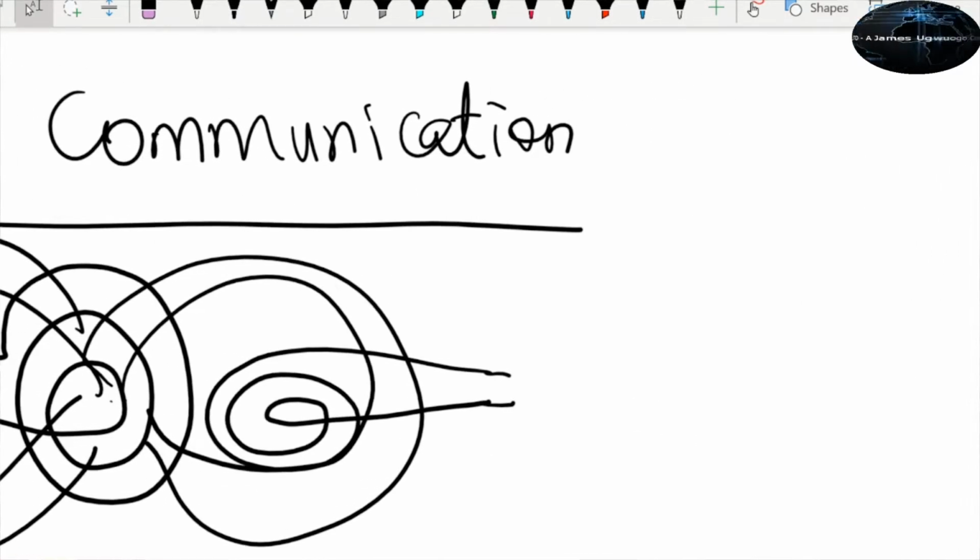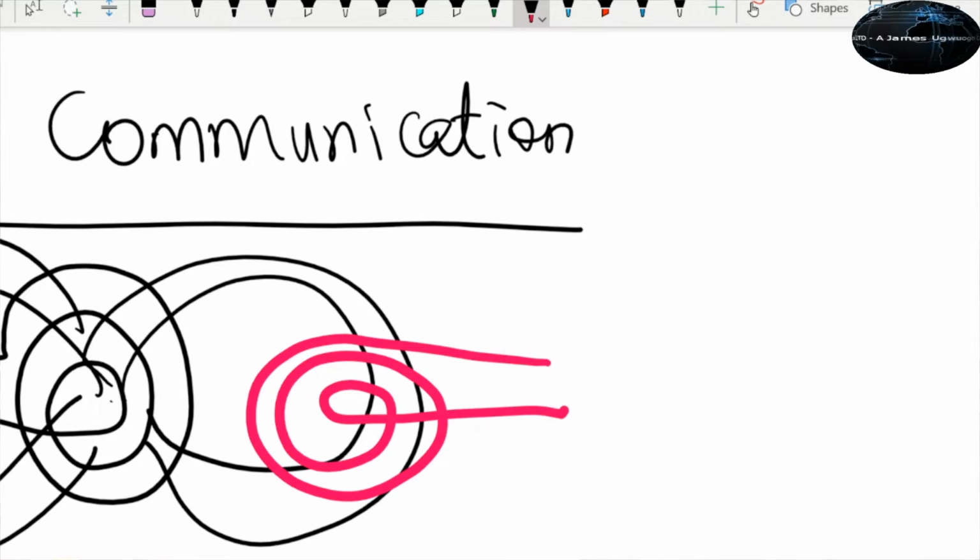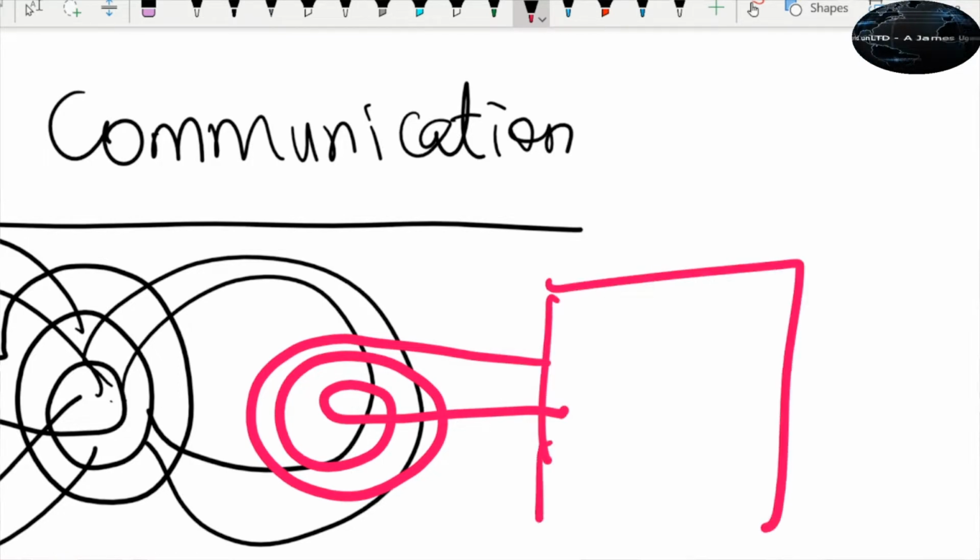The same principle of operation as your transformers. So I'm just going to use a different color for the second coil. Now there'll be a circuit here to optimize the power. This secondary coil will be a resonant circuit. To optimize the frequency and the power, to optimize maximum power transfer, they have to match impedance and also frequency. So this coil and the capacitor will form a resonant circuit.